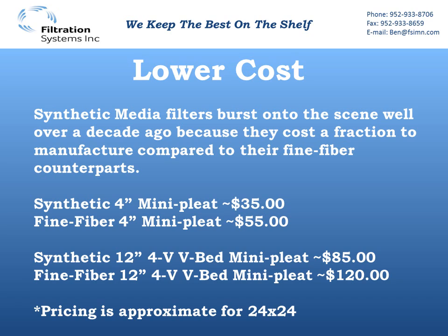When we look at generic pricing for a MERV 14 synthetic 4-inch mini pleat, it's only $35. Compared to its fine fiber counterpart, which comes in about $20 higher, right around $55. When we go to the upper end, the 4V V-bed mini pleated filters, synthetics again are right around $85 a piece, whereas the fine fibers are considerably more, hovering around $120 a piece.